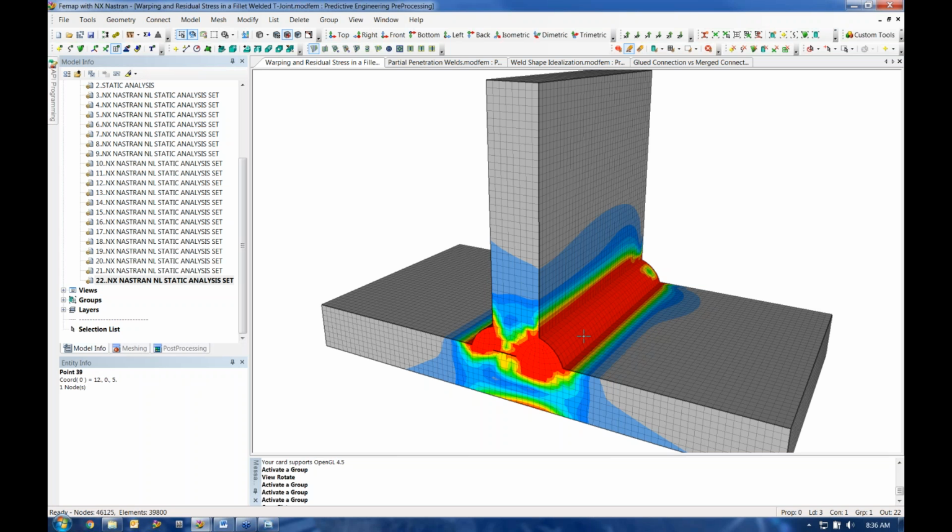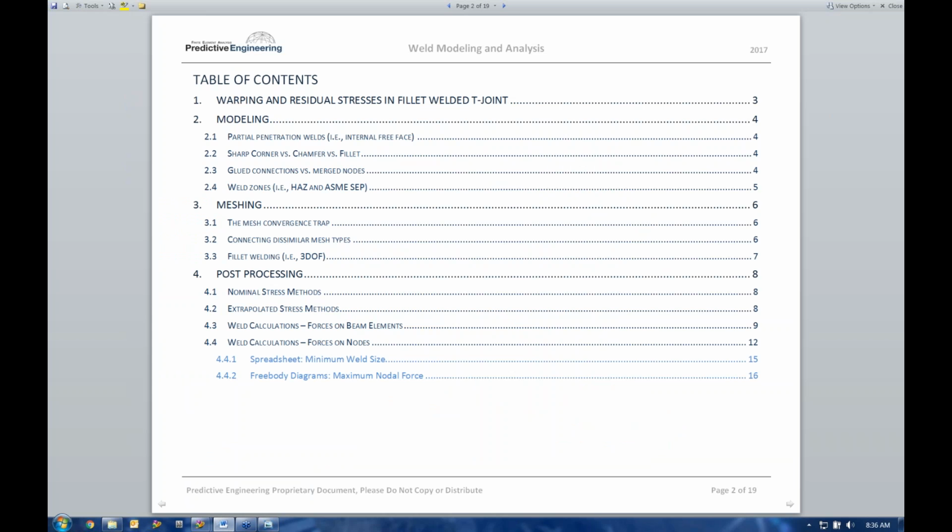Two, when you get into the fatigue side of things, is the scatter. There's a lot of scatter there, so we're not necessarily trying to get the exact right answer. It's based on probability. We're trying to get as close as we can given the information we have. Another thing, especially concerning fatigue, is the slope of the fatigue curve. Small changes in stress are going to be huge changes in fatigue life. So getting accurate stresses is important, but we also have to remember that there's a lot of error involved there.